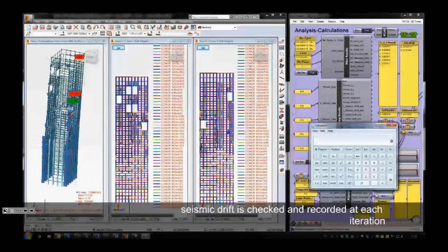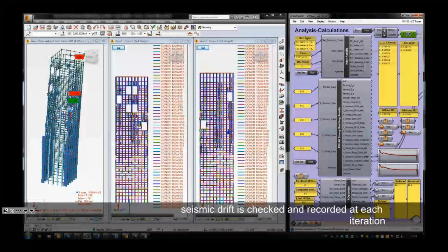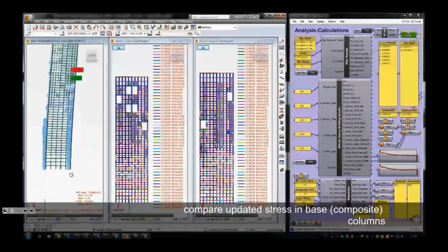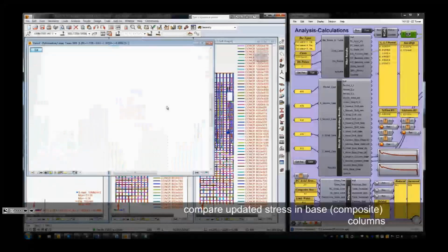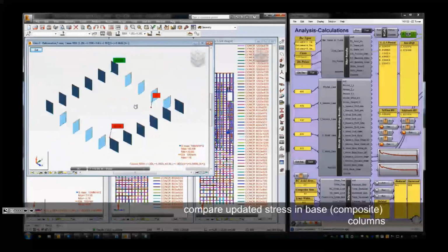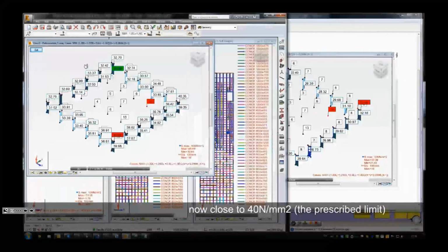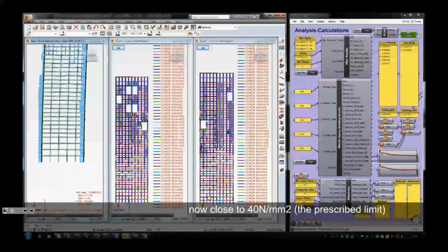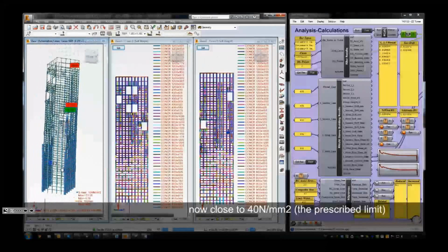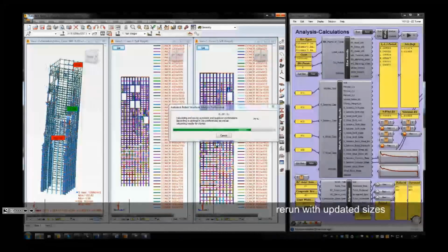They also wanted us to reverse that process: start with no structure, and put it on a predefined grid where the columns and their neighbours were overstressed. By doing your own optimization, you can quite simply put together different rules to see what effect they have on the building. You may not be surprised to learn that the actual result was lots of columns at the base that are quite big and smaller at the top.